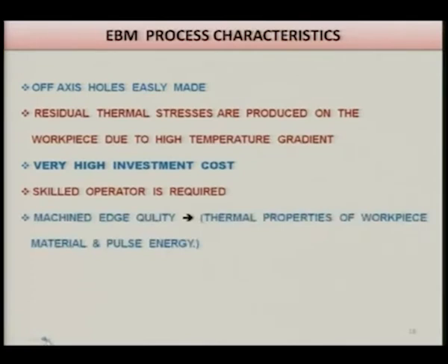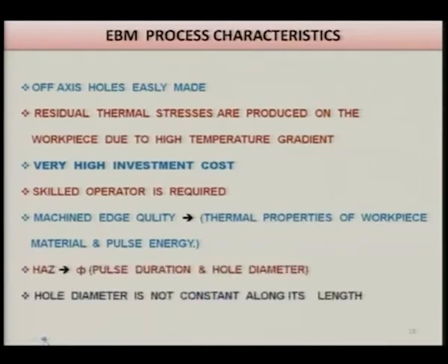Machined edge quality is a function of thermal properties of the workpiece material and pulse energy, and heat affected zone is a function of pulse duration as well as size of the hole being machined, and hole diameter is not constant along its length. Although we expect that the diameter of the hole should be constant, the walls of the hole should not be tapered, normally it is not the case.